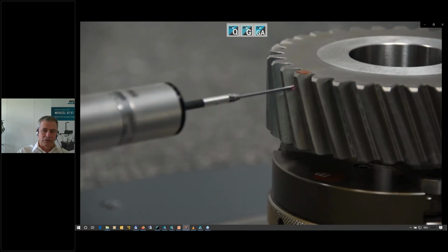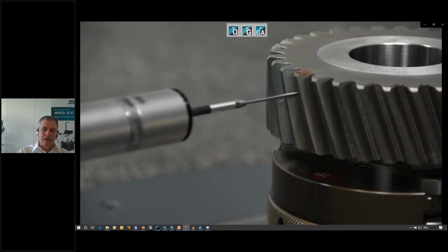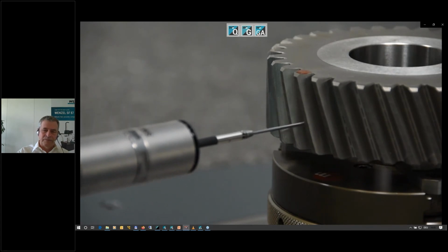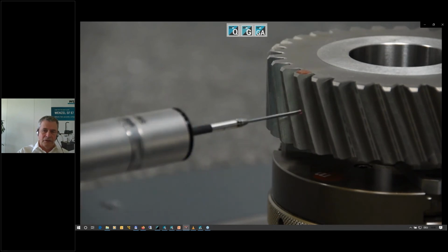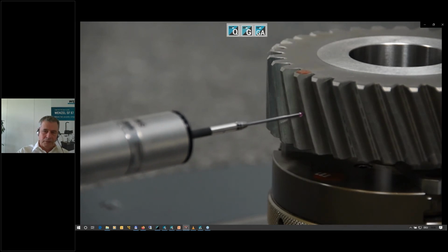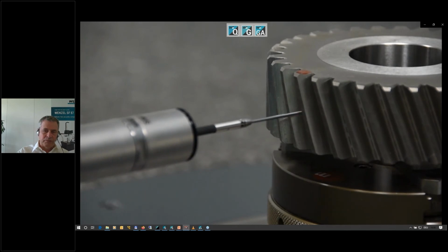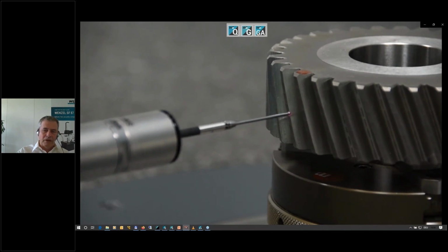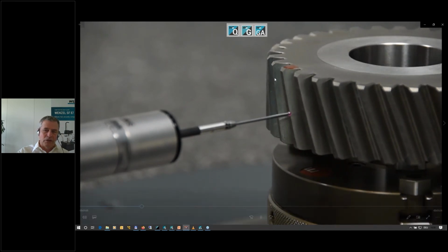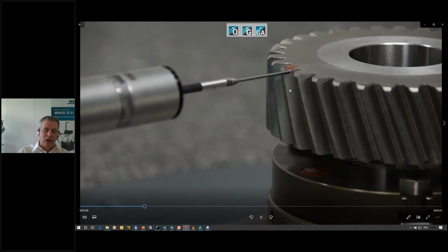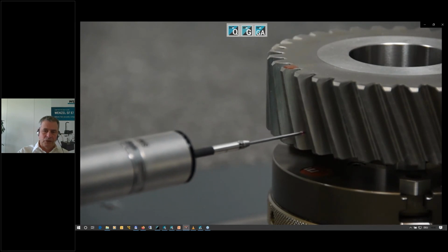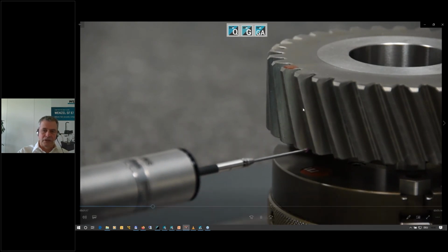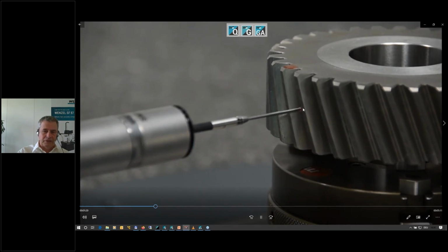Now the measurement starts. So it starts with a lead check. Okay, after that it continues with a profile check on the right flank of tooth number 1. And after that, you can see it clearly, it does another check. So the last check here is a pitch check. And this means when we have one revolution, 1/360 of the gear, all the measurements you've chosen are perfectly made. So no need for another revolution to do a pitch check or so. So we finished the revolution, 360 degrees, everything is done.